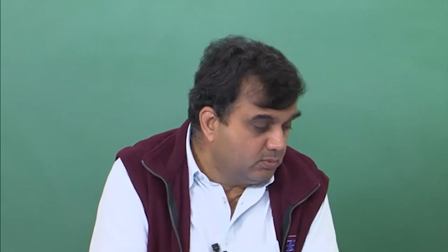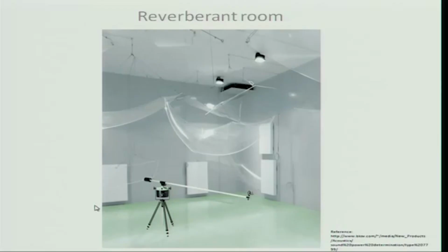So what does an impedance tube give? It gives us the value of Z, which is the impedance, and I know that the value of Z is dependent on the reflection coefficient, right? From that I can calculate the value of absorption, because whatever is not being reflected is getting absorbed. We can also use these reverberant chambers to measure alpha for different materials. And how do we do it? That is what we will discuss in the next several minutes.